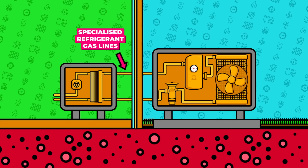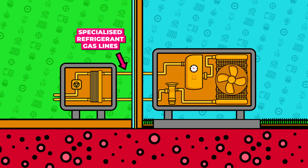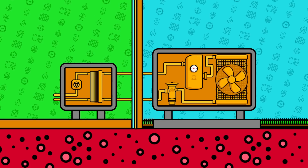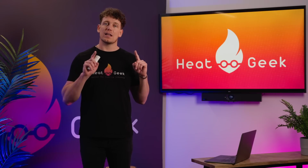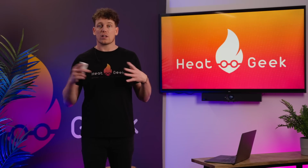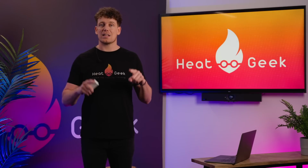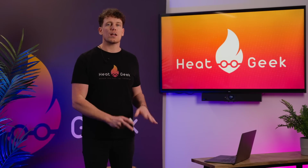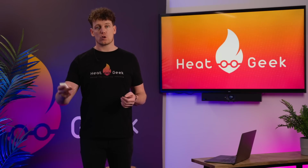A refrigerant gas is what carries the heat between the two units and needs to be carefully injected into the system by a fridge gas engineer. Again, the indoor units can either have fan coil units, like the unit outside. These are known as air-to-air heat pumps, or they can be connected to water to run around radiators for air-to-water heat pumps. The main advantage of these split units is that you can site the indoor unit quite far away from the heat source, and so they're very helpful for commercial buildings.